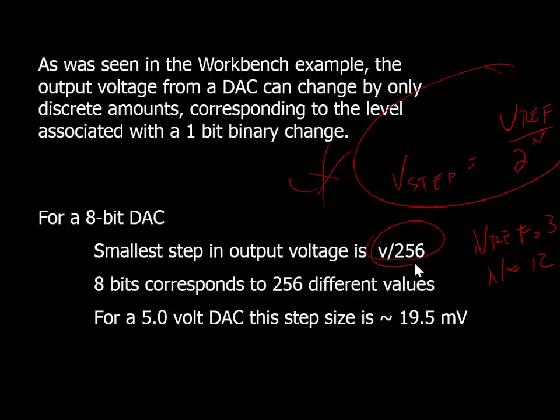You may be asked another question that says you need a resolution of exactly how many, and this is also often referred to as the voltage resolution. How accurately can we represent that? 12 bits is actually pretty accurate, because that's 3 volts divided by 4,096. So, okay.